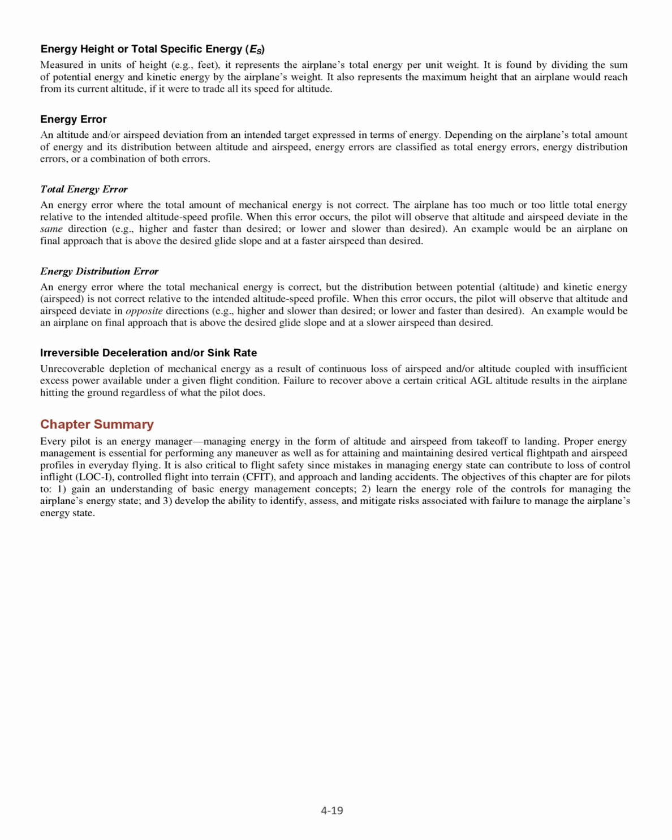Chapter Summary. Every pilot is an energy manager, managing energy in the form of altitude and airspeed from takeoff to landing. Proper energy management is essential for performing any maneuver as well as for attaining and maintaining desired vertical flight path and airspeed profiles in everyday flying. It is also critical to flight safety since mistakes in managing energy state can contribute to loss of control in flight, LOC-I, controlled flight into terrain, CFIT, and approach and landing accidents.